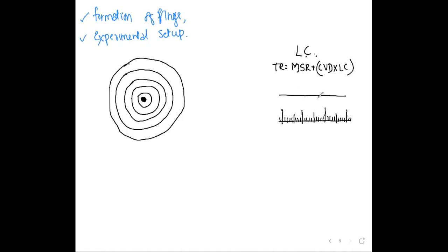And one more scale will be above here. That will have some other divisions like this: 1, 2, 3, 4, 5, 6, 7, 8, 9, 10. Divisions can be 10 or 50, something. So the above scale is movable. This is the movable scale, and this is the static scale. The static scale we call the main scale. This scale we call the vernier scale.